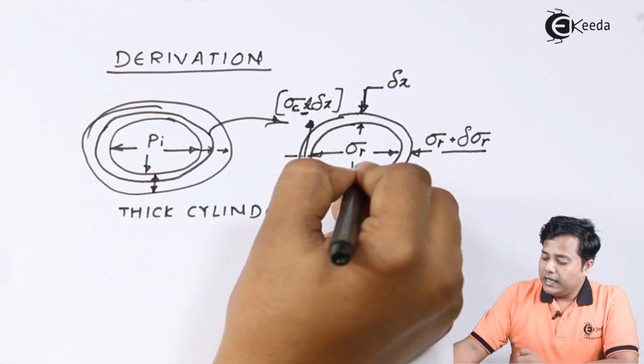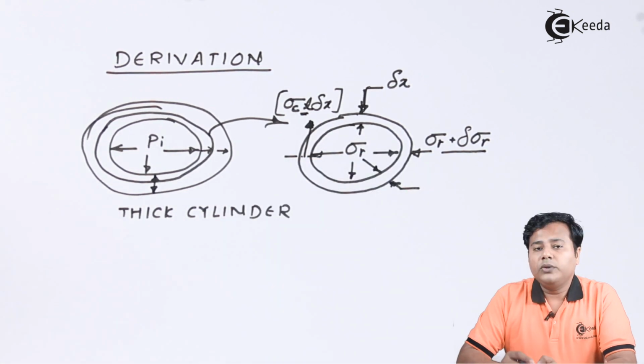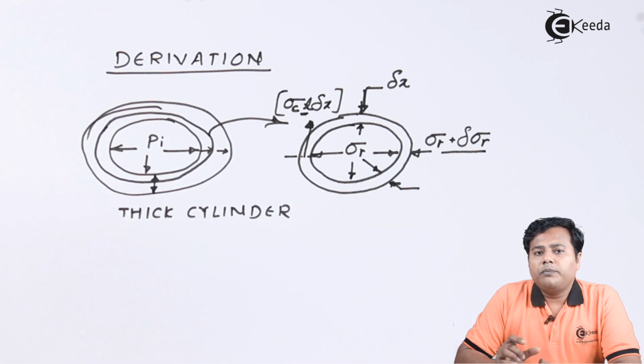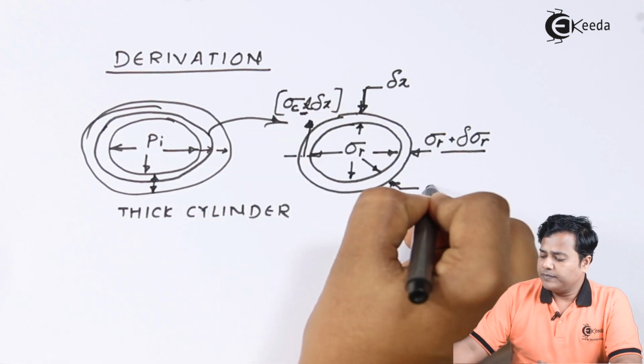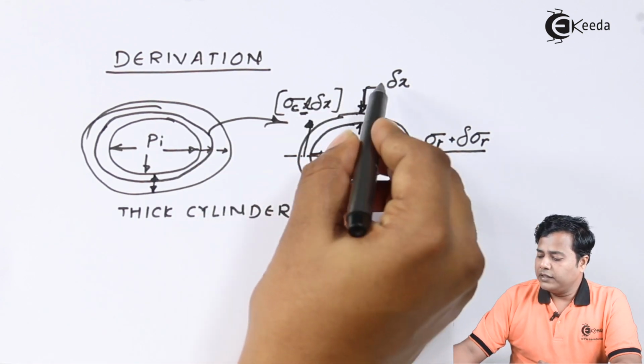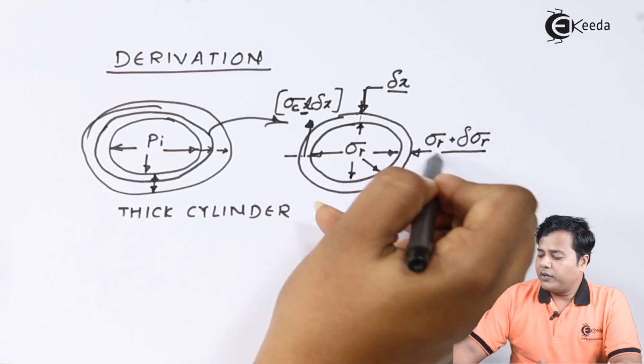Apart from this, let us consider this as the radius of the strip, the inner radius, of course. Now guys, you need to understand that the internal pressure is the actual source of stresses. Internal pressure acts with more intensity on the inner surface, and that's why the inner diameter is always more prominently considered for the design. So let's consider the inner radius, which is x in this case. And just because it was x, we had considered this thickness as dx or delta x, and from there we came across this particular stress.